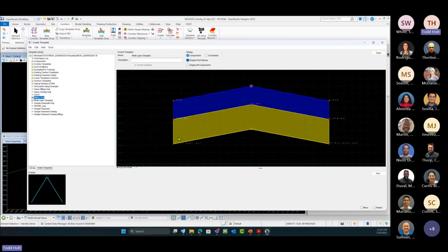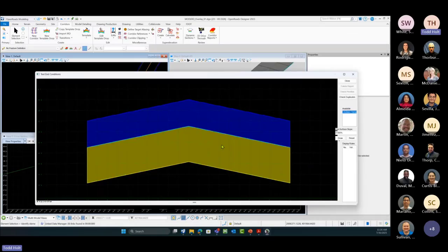So we have our premium overlays, we have our economical overlay. So now I need to come in and do our milling. And I'm going to drag and drop that. We're going to put that to the CL bottom. I'll put that milling component in here. And now if we test, I did miss that one. So we have our pavement design, we have our premium overlay, we have our economical overlay, we also have our milling.